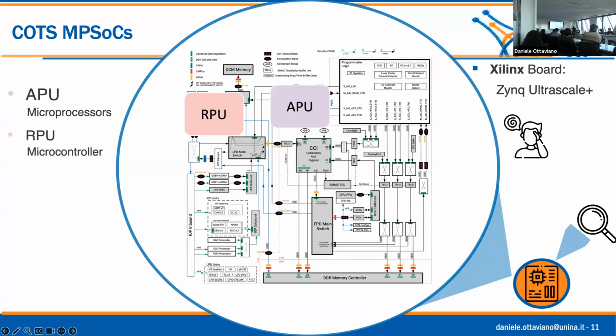Yeah. I just want to make sure I heard you right. So the APU, the application processing unit, can also run an OS there. Presumably Linux, whatever. Yeah, you can run an OS, you can also run a hypervisor. So specifically in this board, if you know this kind of ARM processor, there is a quad-core Cortex-A53. This classical processor we can also find in our smartphones, for example.